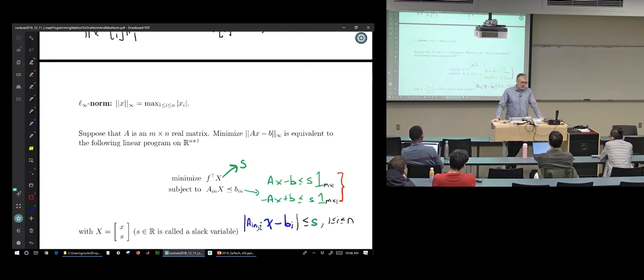The problem they were having is that the engine would not idle smoothly because you would get imbalance between the two banks. And so I recognized that this was a periodic control system, that I could lift it up in a certain way, and then I reduced everything down to a root locus problem that the engineers could understand.